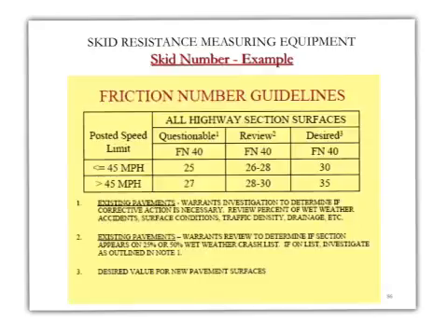So in other words, this table just gives you the minimum, medium, and desired value for friction number, or skid resistance number, for roads with speeds less than 40 miles per hour, or if you have more than 45 miles per hour. So picking the second row here, if let's say on a highway the speed is 65 miles per hour, which is more than 45, then the desired skid resistance number would be 35.